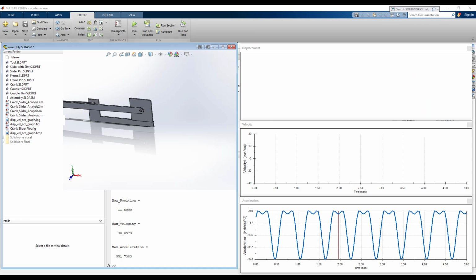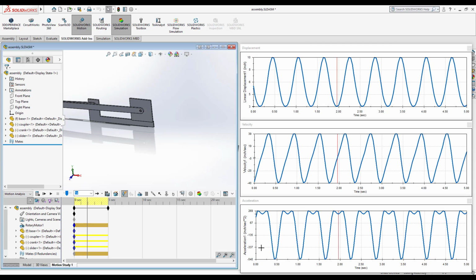And to double check the work, we also simulated it in MATLAB. This is not exactly the same crank slider that we're using, since there's probably going to be a slot in the slider for an extra degree of freedom, so that when it bottoms out and changes direction for the coupler, it's not going to cause an excessive amount of force with retracting it back suddenly. And that just makes it so it's a little bit smoother.